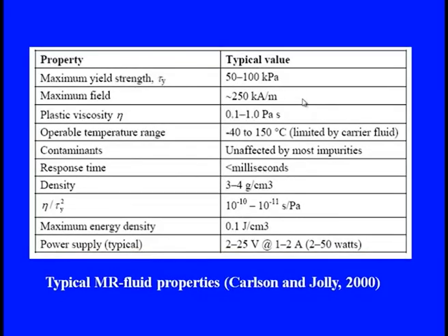When we are going with the MR fluid, there are various properties documented by Carlson and Jolly in their paper in 2000, in which a typical MR fluid can give a yield strength of almost up to 100 kilopascal, where the maximum field can be 250 kiloampere per meter.